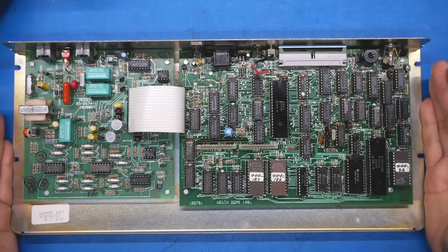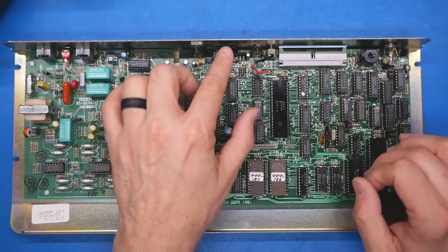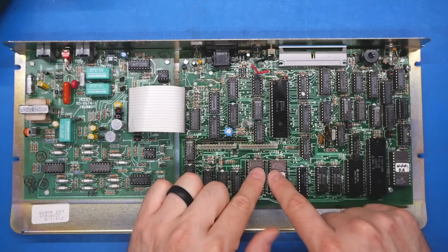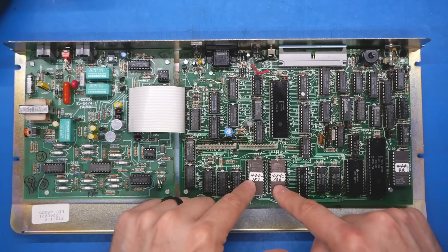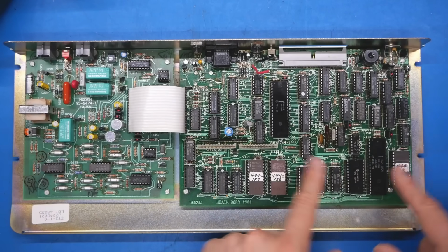Right, so back to the repair of the ZT-1. I never got this thing working. It seemed at the end, after fixing a shorted tantalum and some bad traces, the system would try to boot a little bit and then it seemed to be stuck. Like the CPU was stuck in some kind of a loop. It was accessing both of the ROM chips, but the machine wasn't actually accessing any of this stuff anymore.